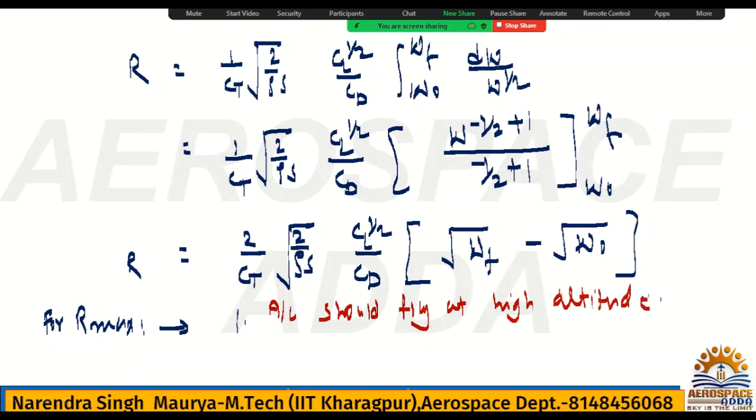For that reason, generally, if you check commercial aircraft, even if you want to go from Bangalore to Hyderabad, where the distance is less, the aircraft is going to fly at 11-kilometer altitude in the stratosphere. Why is it going to fly at 10, 11, 12, 13-kilometer altitude? It could still fly at 4, 5-kilometer altitude only, because Bangalore to Hyderabad or Bangalore to Chennai is very near, no? So why does it first climb to 11-kilometer altitude and then cruise? Because only at high altitude can you maximize the range for the same amount of fuel. So that is one reason.